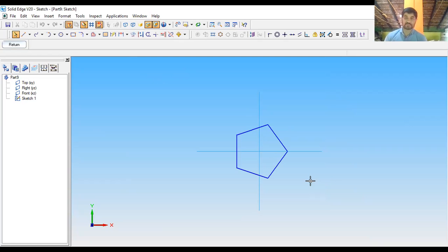If this option is not there, then every time you have to draw a line, maintain 72 degrees, and keep on drawing. It will take time. Instead of that, you can use the macros so that you can draw the polygon directly. This is about the macros. For this profile, you can make anything, an extrude option or a cutout option, anything you can do.